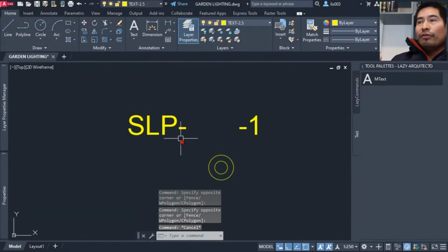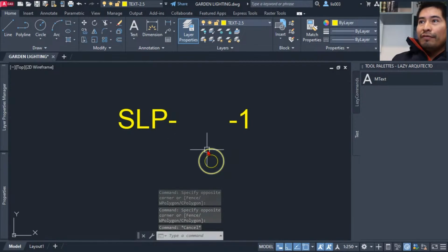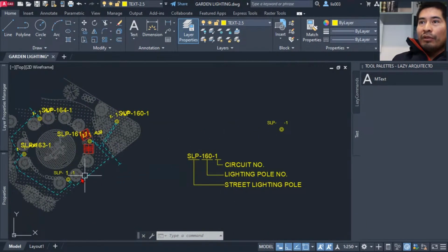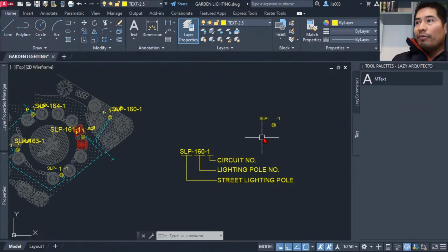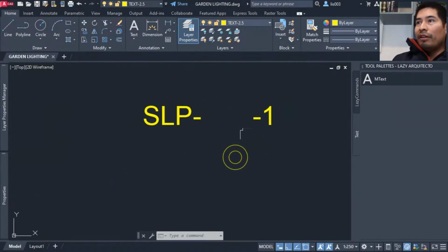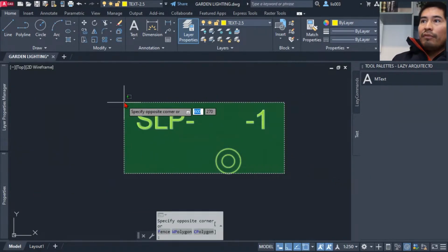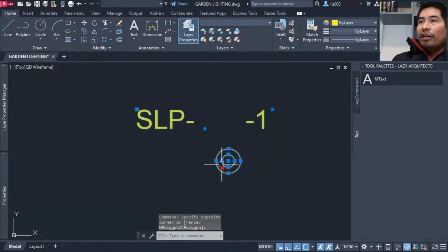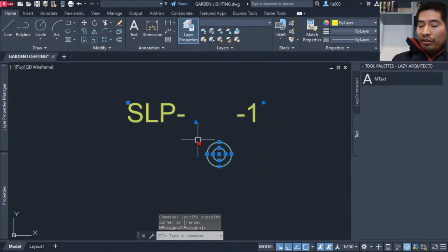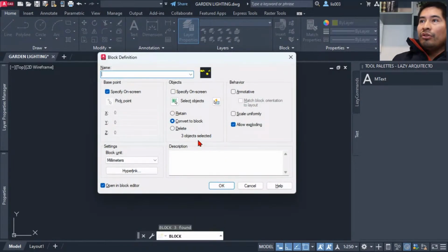So let's do it differently now, so that I don't start with his existing block, but start fresh. I'm going to select all of his geometry and create a block using the B shortcut. I'm going to call this 4M_pole, like so, using the underscore.